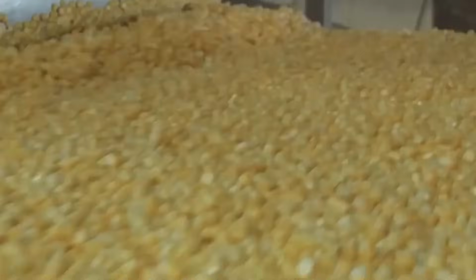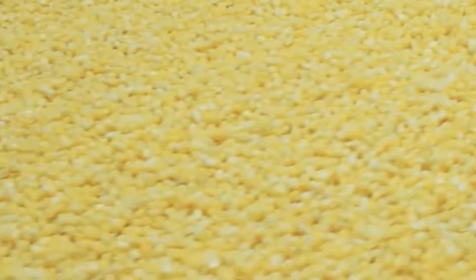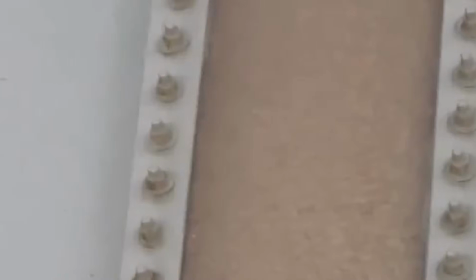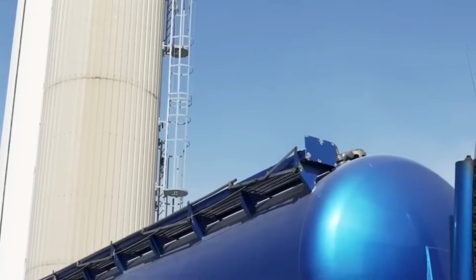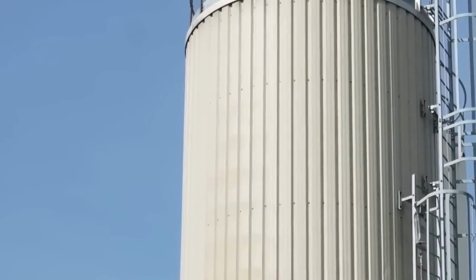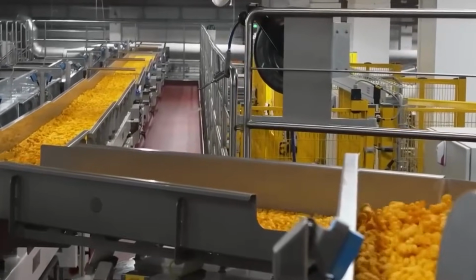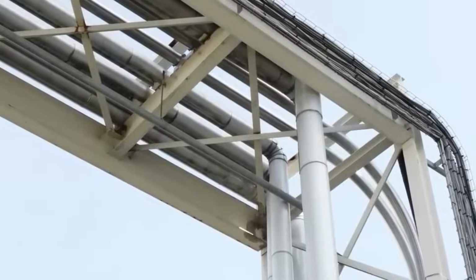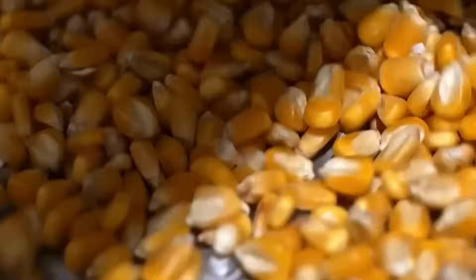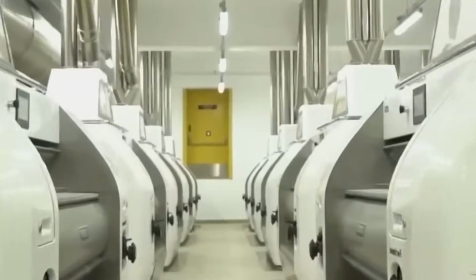Under these conditions, the starch within the cornmeal fully gelatinizes and the protein matrix denatures, forming a viscous melt that is cohesive and plastic in behavior. At the final die plate, the pressurized melt exits into atmospheric pressure, causing rapid vaporization of internal moisture. This sudden expansion creates the puffed structure of the Cheeto.